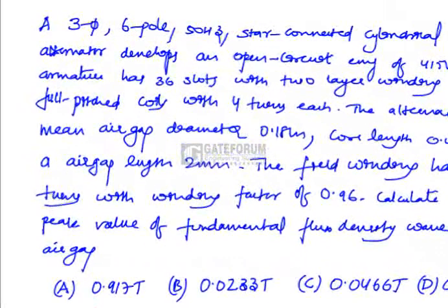Okay, in this question we have to find the peak value of the fundamental flux density wave in the air gap. This is a star connected cylindrical rotor alternator which develops an open circuit EMF of 415 volts. Now let us first calculate how many series turns per phase there are.